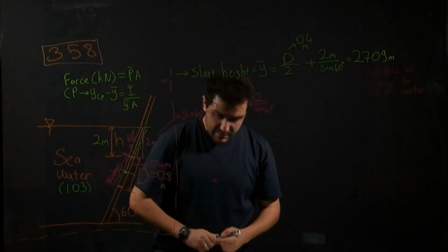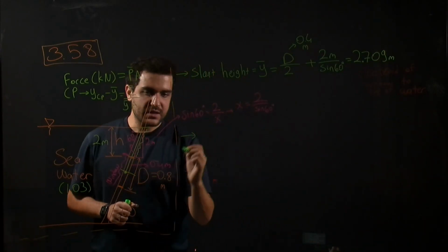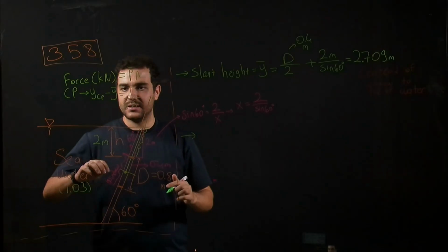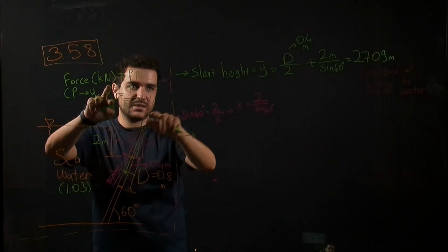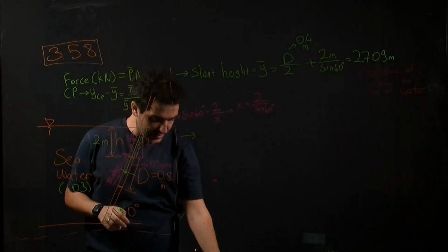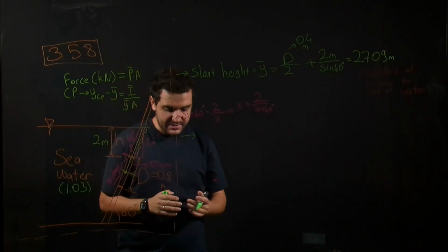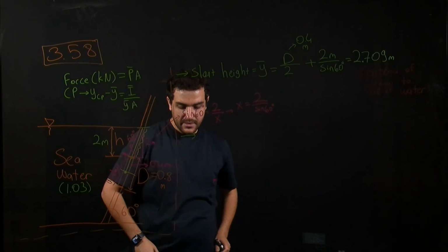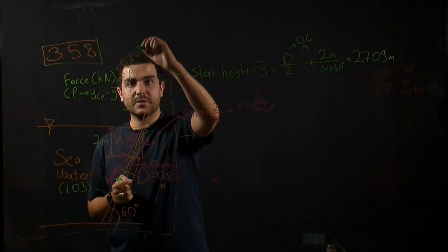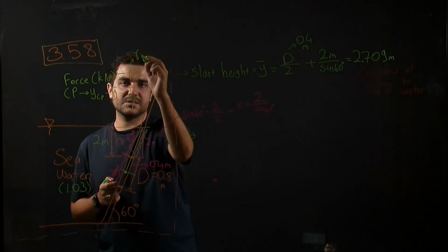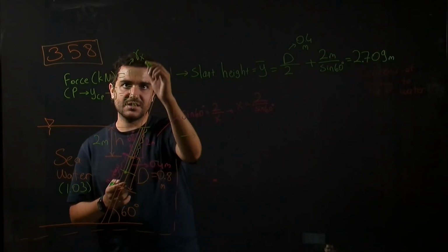Okay. So the next one we are going to calculate is, and actually we already calculated this value, which is slant height, and now we will get depth of centroid. This is required because to calculate pressure here, we are required to find specific weight times depth of centroid.